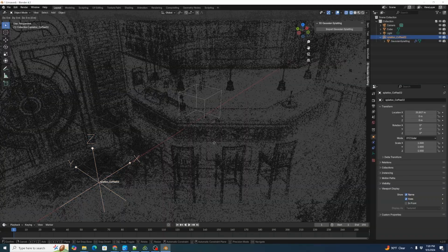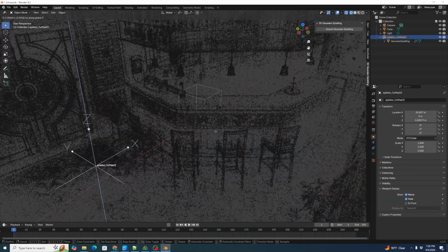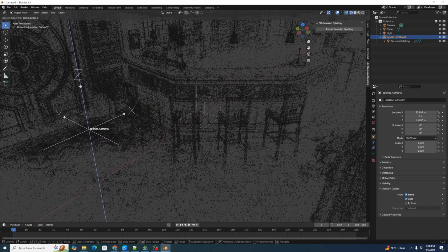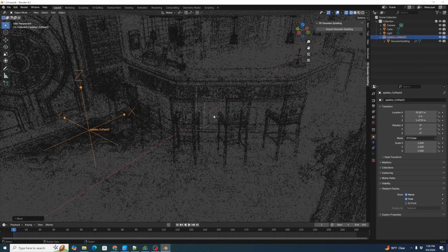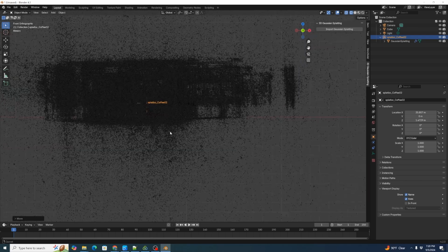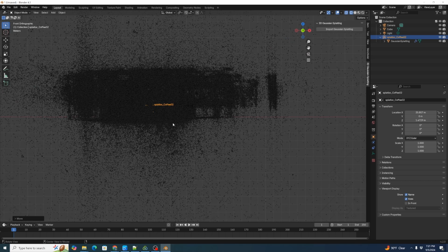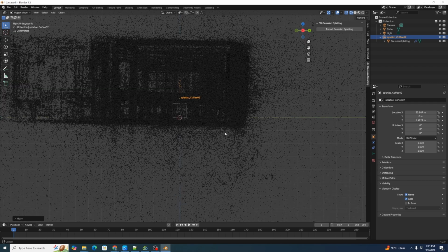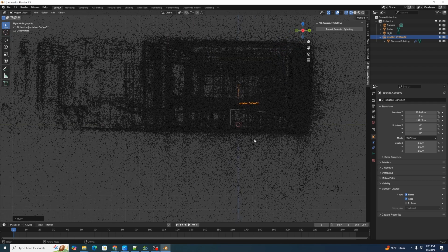And we're going to hit GZ. That's going to isolate the motion of our splat locator to the vertical axis. And let's see when we've aligned to the floor. I'm going to hit 1 on the numeric keypad, and let's scroll back. And actually, we see we've got a couple of problems here. Before we even do that, we can see the splat is a little bit misaligned rotation-wise. It's not really flat. So let's do a couple things.